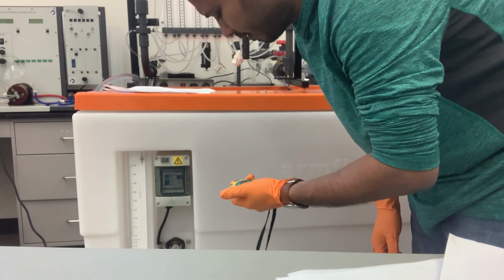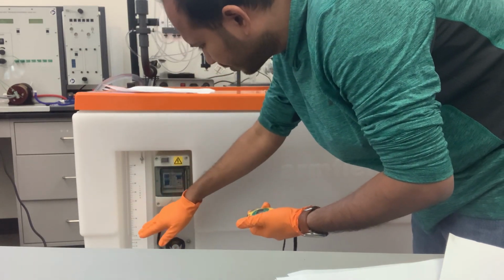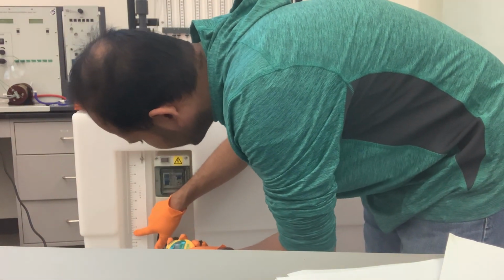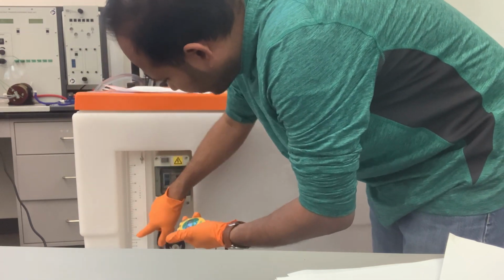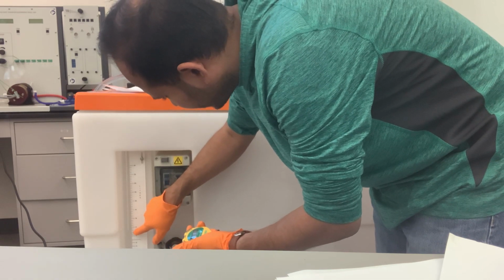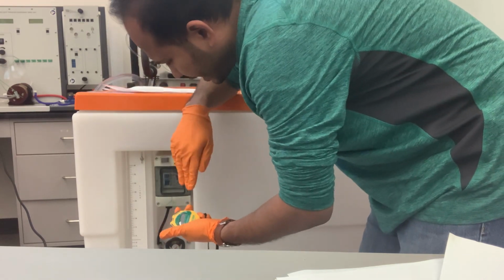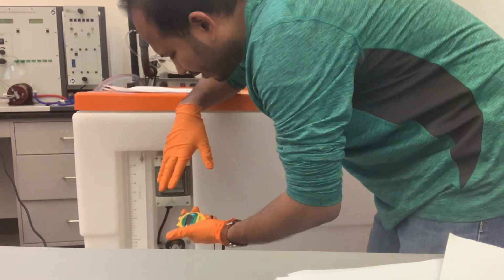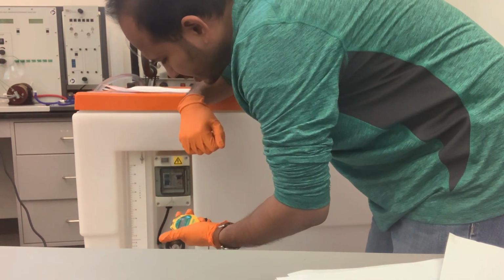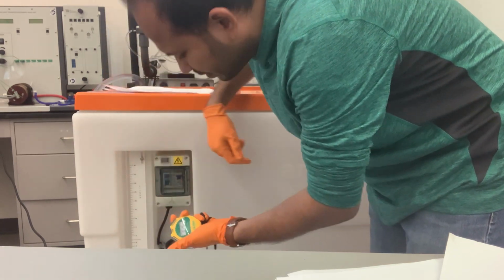So I'm going to measure how much water filled up given a time, and I can measure the flow rate. So the pump is running, the water is going up. My goal is to have no more than 17 liters per minute. So what I'm going to do is, when I have a mark, for example now it's 2 liters, I'm going to start, and what I'm going to take is how much time it takes to fill 5 liters. So it was here 1, 2, 3. So how much time will it take to be at 7 liters. If I can get 5 liters in 20 seconds, then I will have about 15 liters per minute. So I will be well below the range of 17. So I'll be good to go. So I'm only at 22 seconds and I'm about 17, so I'm good to go.